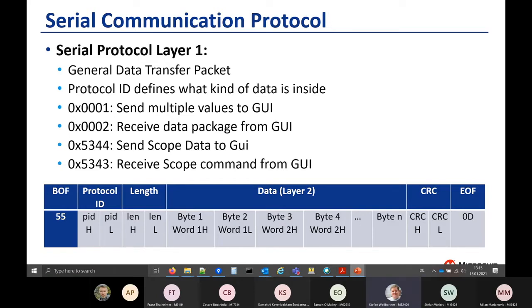Also, we can trigger such an event from the GUI. That's a little bit of a delay, but this trigger command can also be embedded into the source code. We used it, for example, in the 4-switch buck boost in the startup. So then we can nicely see some voltages or currents in the startup phase.